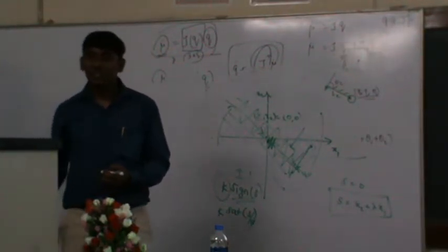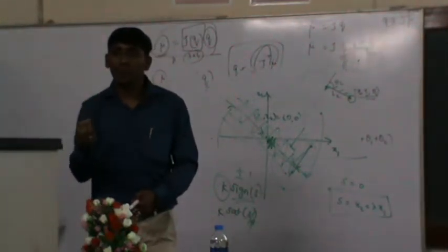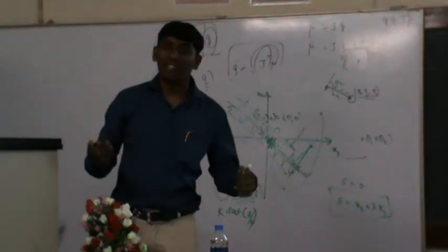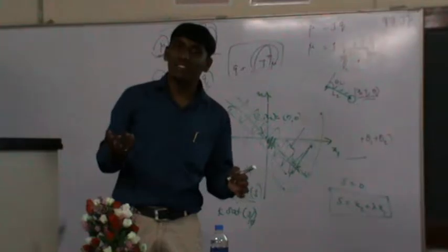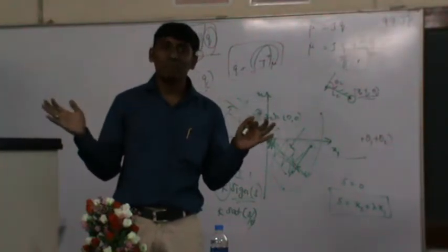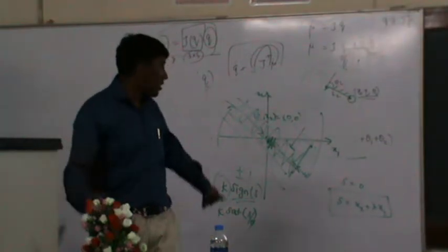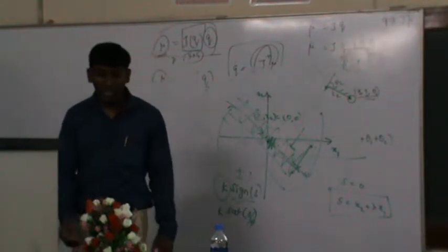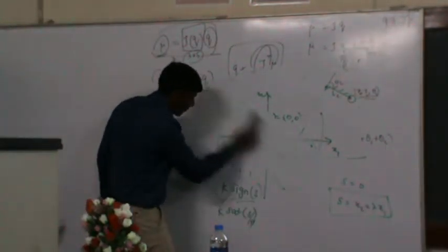Everything depends on these. Theoretically, if you do simulation, your step size is probably 1 millisecond or 10 millisecond, and it may work. If you increase it to 100 millisecond or 200 millisecond, you can see that the response is very poor with the same control gains. So that's the idea here. What we thought is, we'll try to merge sliding mode with the PID.